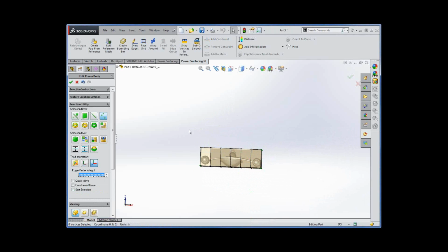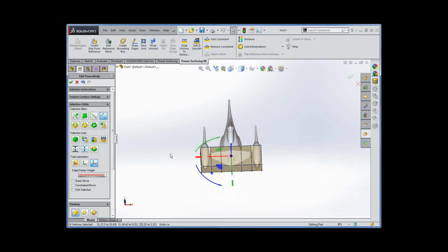And that's one of the things that's kind of difficult if you do some of the more manual creation methods. Sometimes if you work on this piece and you work on this piece, it may be hard to connect them up because the edges don't line up. They might not be the same number on each side. This method allows you to do that. And then you just do extrudes and manipulation of the vertices, just like regular polymodeling. So anyway, that's the one I forgot to show you.